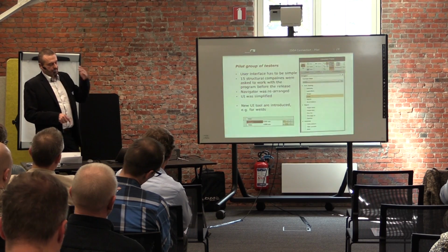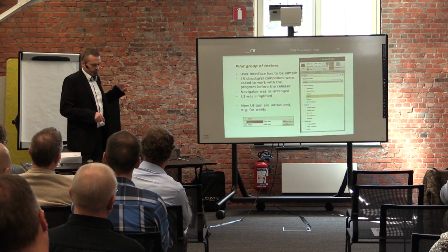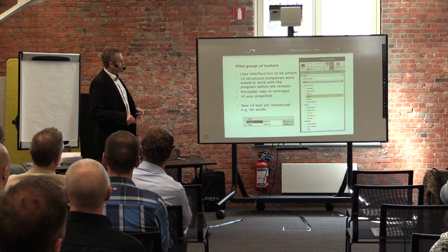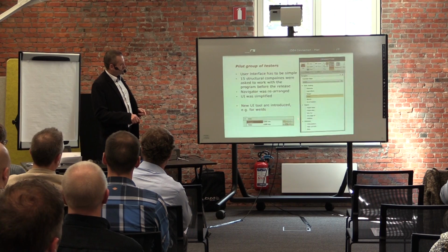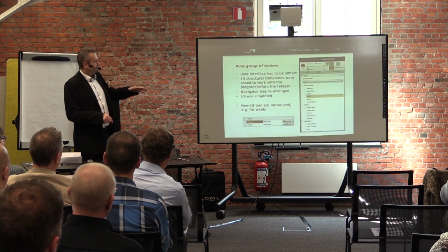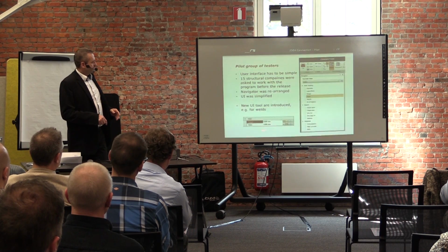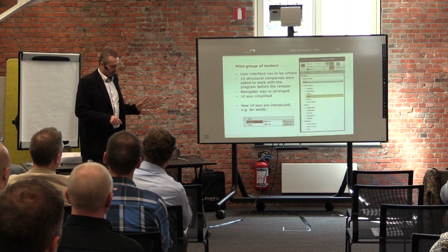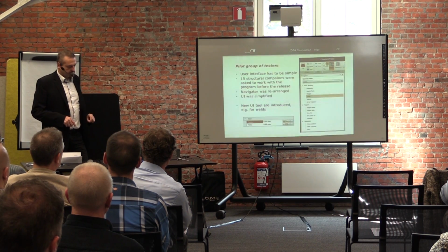There is another example. This is from the new version. We had a lot of comments on the definition of welds. So we now came with a tool where you simply say it is fillet, double fillet, butt, and give the stiffness and the thickness, and everything is much easier than before.